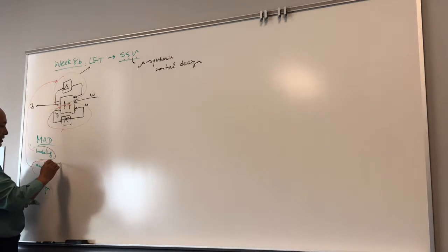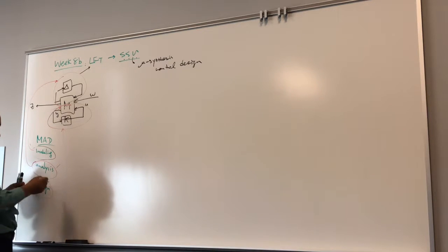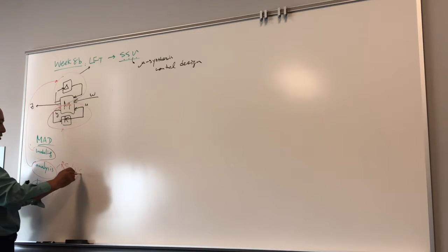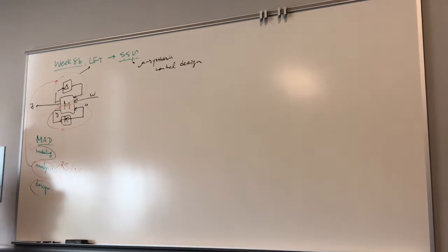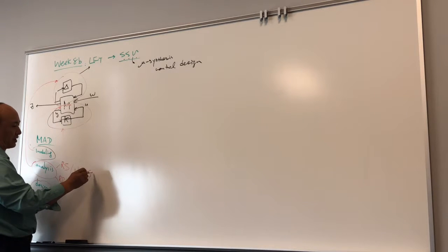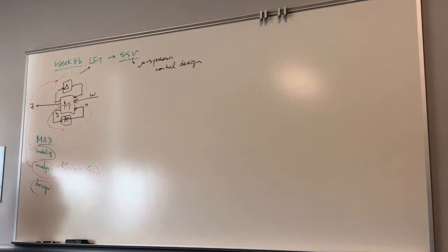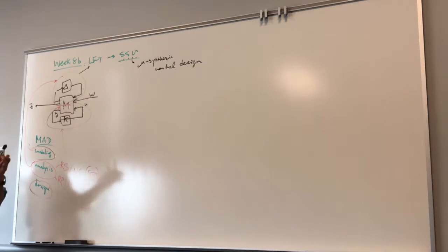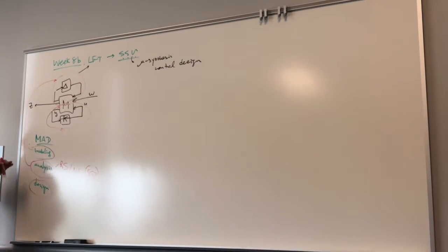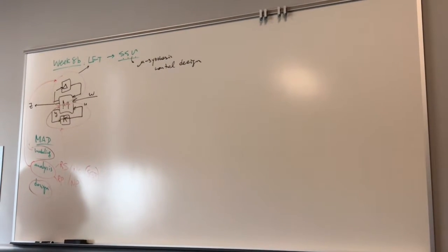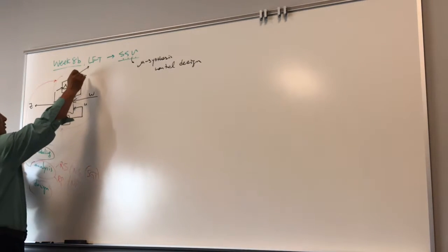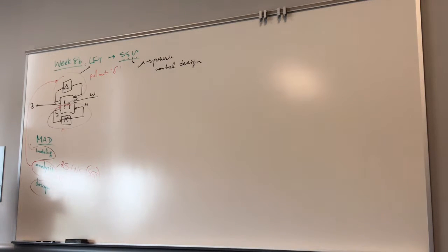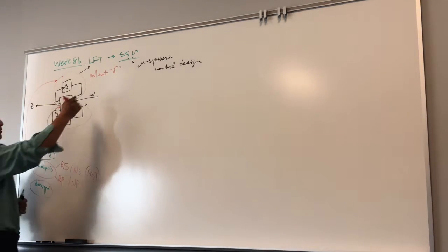So for the analysis, we have already covered in the previous chapters robust stability and robust performance. Of course, we also talked about nominal stability and nominal performance. So the underlying principle is the small gain theorem. The basic idea of the small gain theorem is if the loop transfer function norm is less than 1, there's no way to be unstable. Now in this new chapter, we are talking about how to pull out those uncertainties, such that we can leverage the structure information.